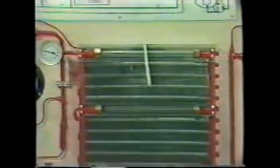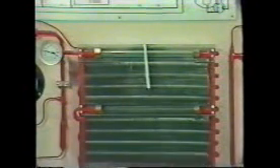In one type, all of the liquid refrigerant is converted to vapor before it reaches the evaporator outlet. A common design is a series of tubes equipped with fins. The tubes contain the refrigerant, which absorbs heat from air or water passing over them. Another kind of evaporator is known as the shell and tube evaporator. Inside this tank are tubes that hold water. The refrigerant contacts the tube surfaces, absorbs heat from them, and vaporizes inside the tank.